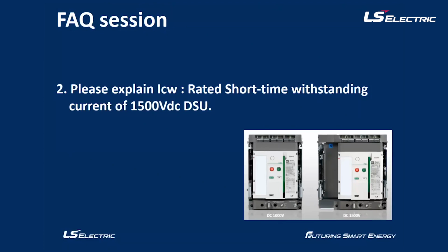So why is that important? The 1500 VDC DSU matters because this system is a combination, based on a fuse with a disconnector switch unit. So when the disconnector switch holds the line, the fuses break the short circuit current.